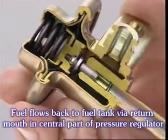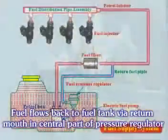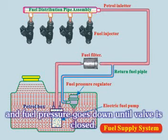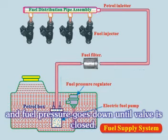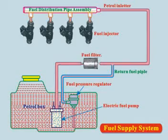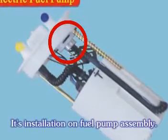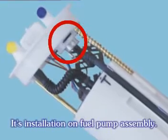Fuel flows back to the fuel tank through the return mouth in the central part of the pressure regulator, and the fuel pressure goes down until the valve is closed. It is installed on the fuel pump assembly.